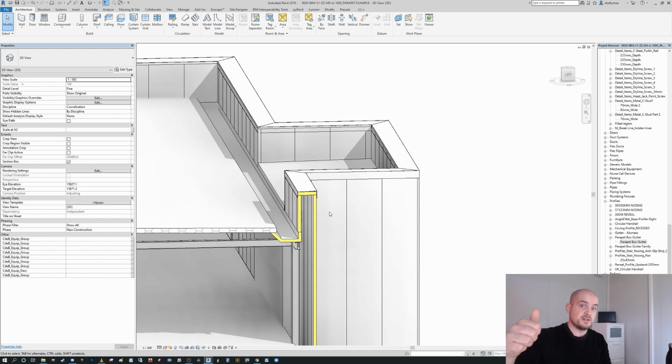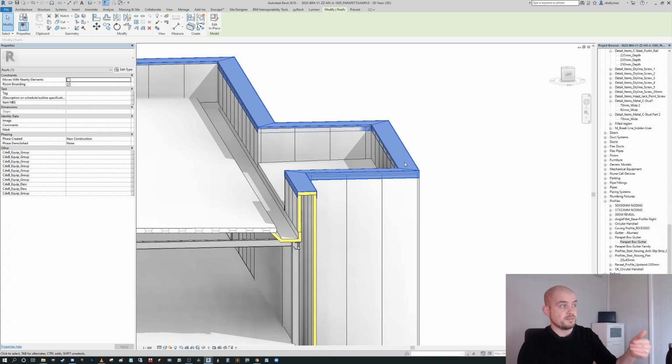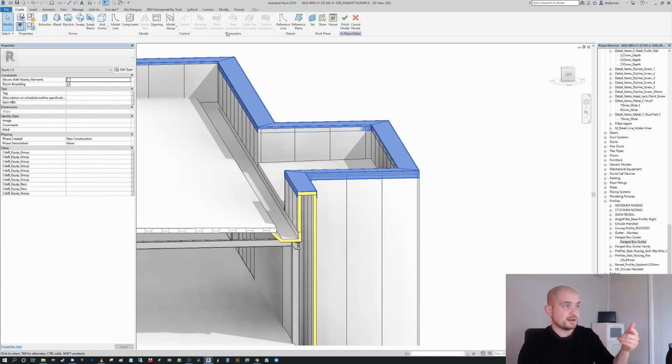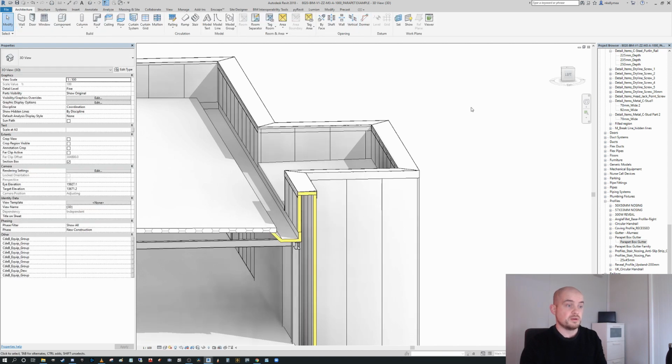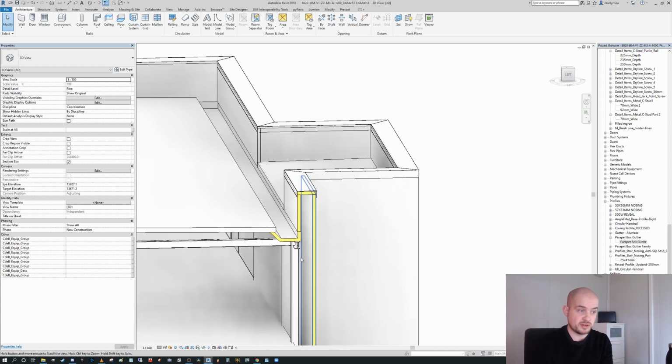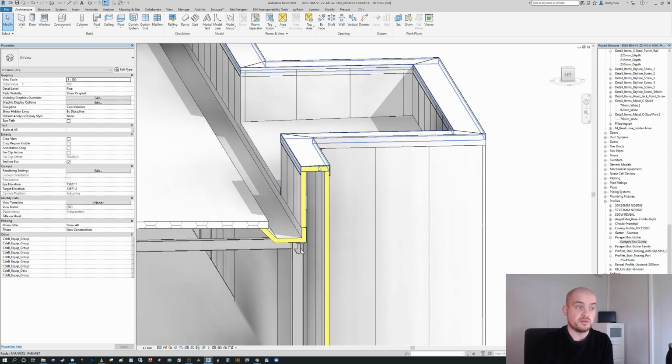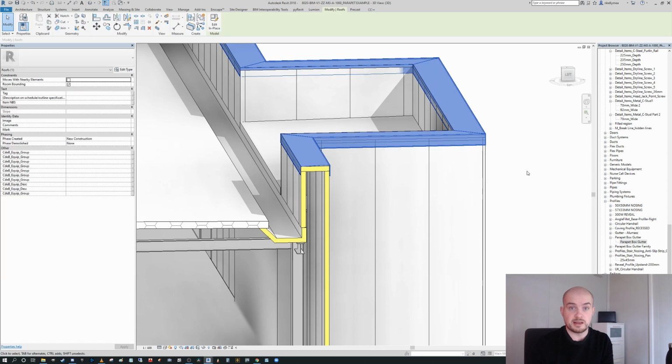But in the next video, we're actually going to go through how you can create your parapet flashings in a similar manner to give a family that is dimension driven, so that rather than what I have currently here, which is an in-place extrusion that follows the path, we have a designated profile that we can manipulate using the type properties, the way I have for the gutter here, to actually drive the parapet capping, sorry, apologies.